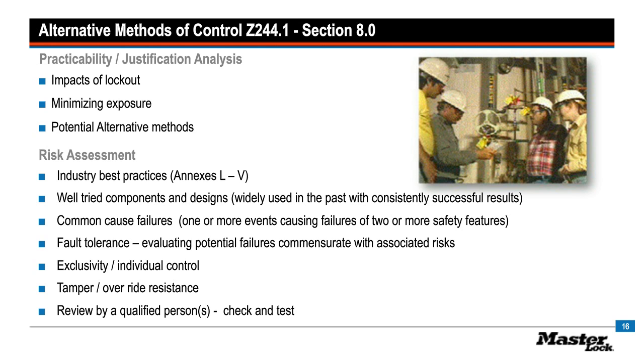We look at tamper or override resistance. How easy is it to defeat or bypass this interlock type protection? In older interlock protection, it's real easy. In fact, many machines have had it dismantled and it no longer protects the doors and the covers on the machine guarding to points of operation and power-driven areas. So there is no doubt that tampering and defeat of interlocks has been a problem plaguing us, and it factors right into why lockout procedures are so important, even if those devices are used to protect workers